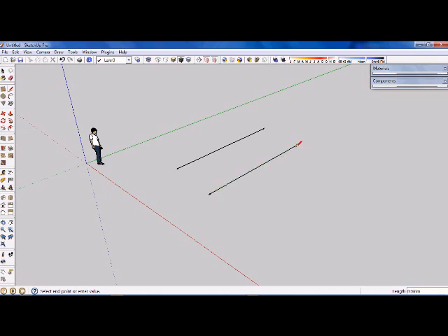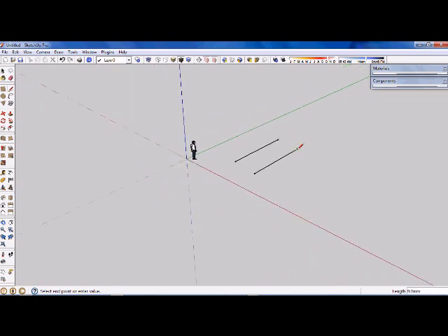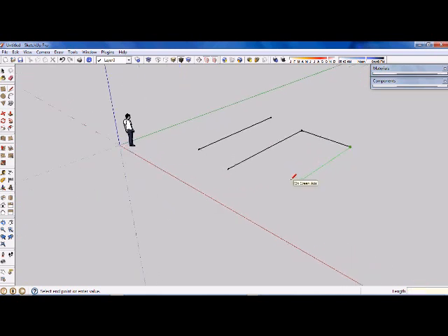So you've got two options. As you're drawing, get the direction right first, and either while you're rubber banding that direction, type the length you want it to be and press enter, or stretch it, rubber band it, then just drop and click the length that you wanted, but then without moving from that endpoint. Most important that you don't move from that endpoint, then type the length that you really wanted.